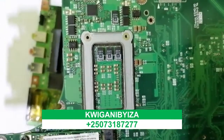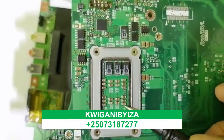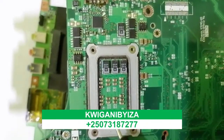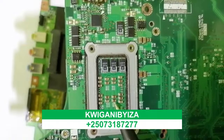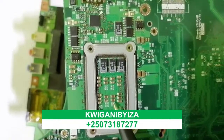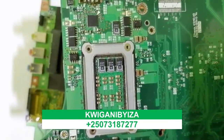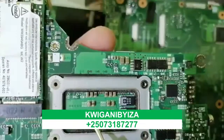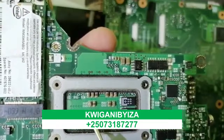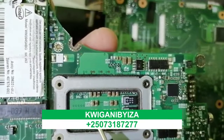So I want to add here that, for example, this capacitor is not like this one in terms of size. If you have a failed capacitor like this one, you should replace it with another ceramic capacitor with the same size and same color, because on ceramic capacitors we don't have values written like on tantalum capacitors or electrolytic capacitors. That's why if you find a failed ceramic capacitor, you should replace it with another one with the same color and same size.